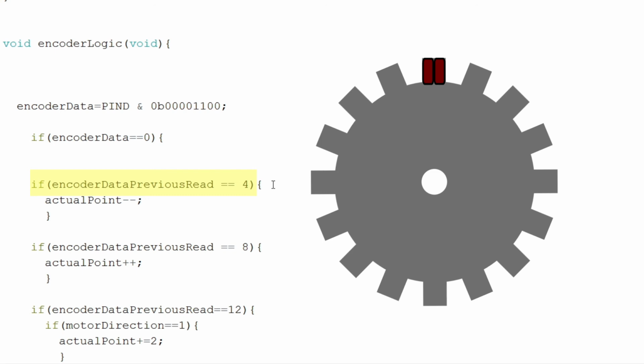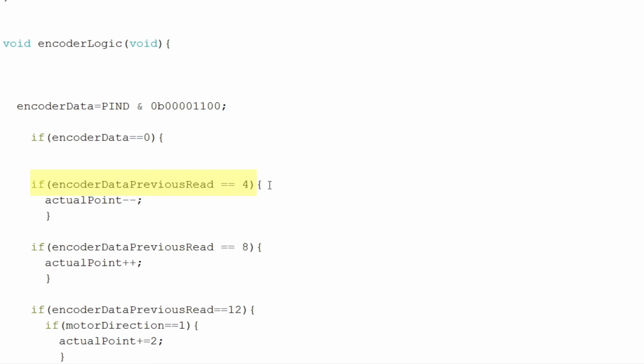We decide one direction is positive movement while the other direction is negative. This is arbitrary, and if it is backwards, simply reversing the H-bridge or motor wiring will correct it. Once the correct polarity is found for interaction between the motor and encoder, the GRBL parameters can be changed to invert the system if it is running backwards. To find the correct polarity of the motor in relation to the encoder, the shaft is turned slightly by hand.